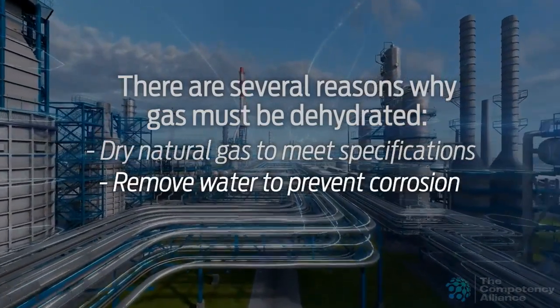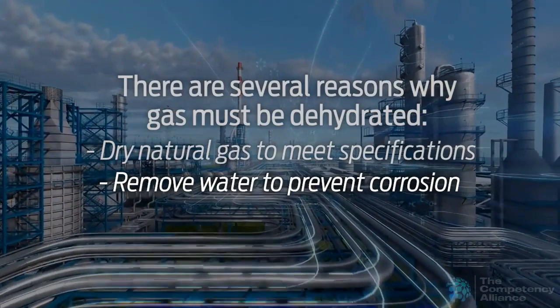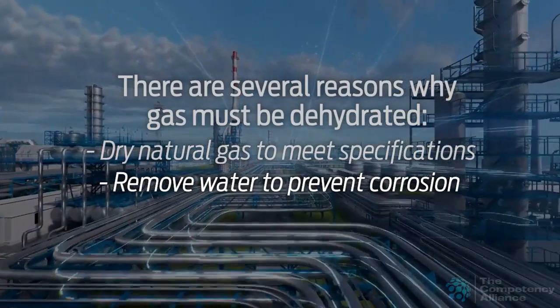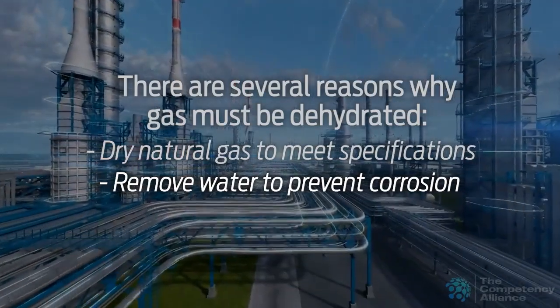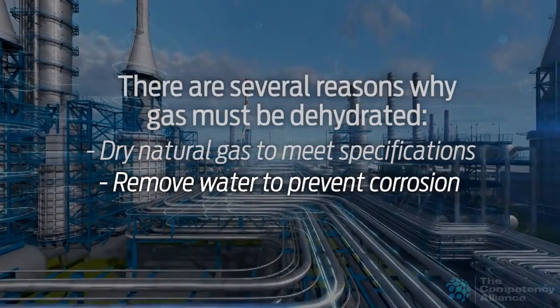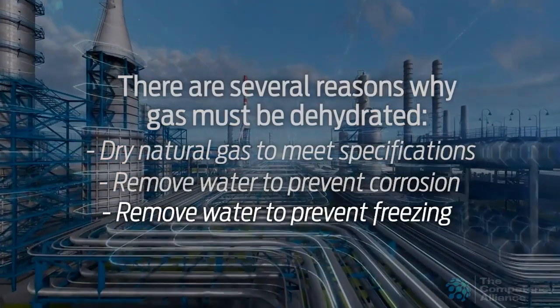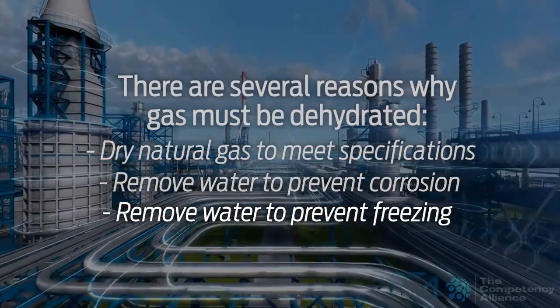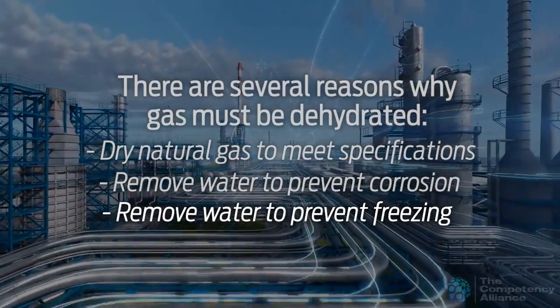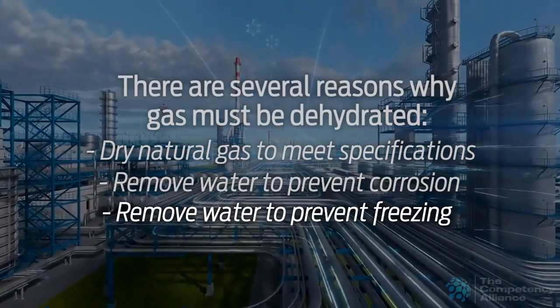Remove water to prevent corrosion in gas gathering systems, gas lift systems, and large diameter trunk lines that deliver gas from offshore platforms to onshore gas terminals or processing facilities. Remove water upstream of low-temperature gas processing facilities and LNG liquefaction plants to prevent freezing in the process.